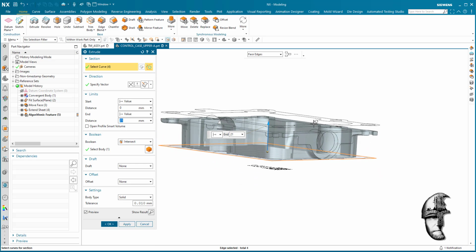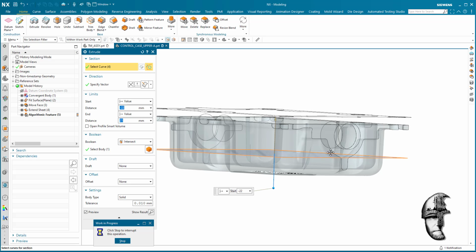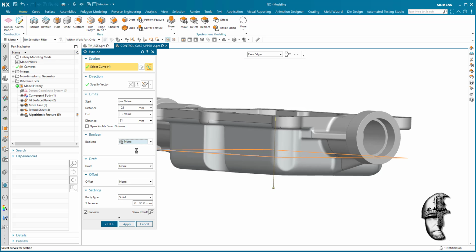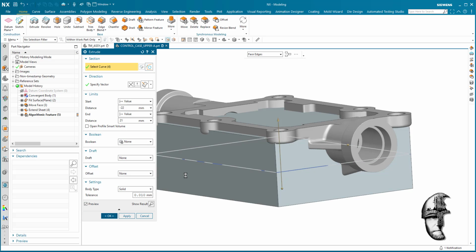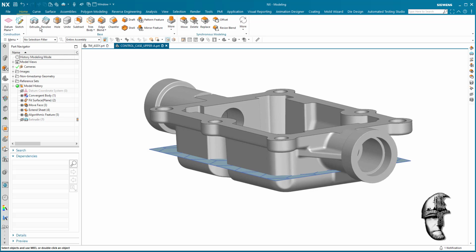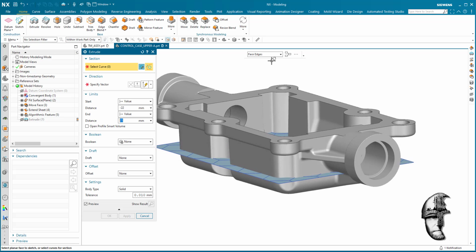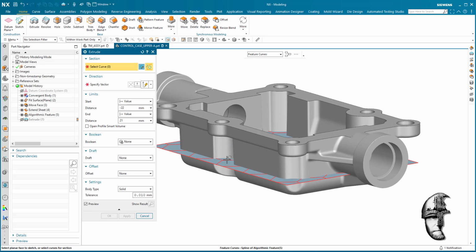It's going to be oversized. It doesn't really matter how oversized, because it's going to be controlled by the hex pattern later on. We're not going to do an intersect. We're just going to create it. That's going to swallow that whole thing there, and we're now going to create yet another extrude. We're going to base it on the feature curves, and we're going to base it on the hex pattern there.